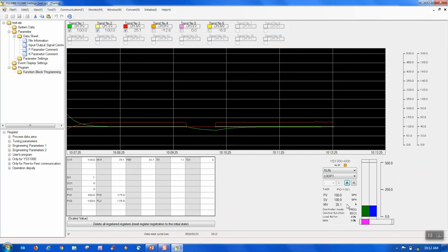And if you watch, you can either watch here for your set point, or the blue bar will change to 400, or you can see it change here as well. So let's open that. See our yellow line, our set point bumps up to 400. Our output immediately changes to try to raise that flow rate to that new set point. And our green bar down here is tracking that process variable change.